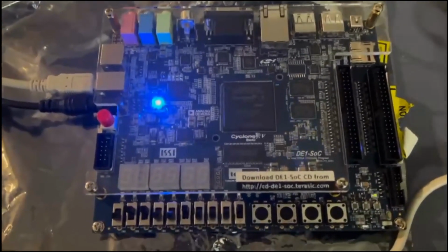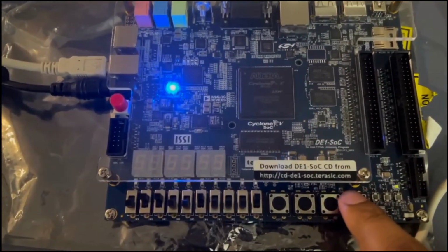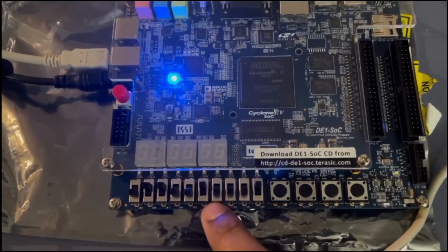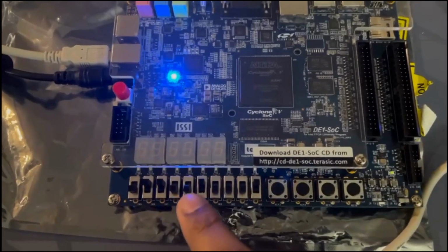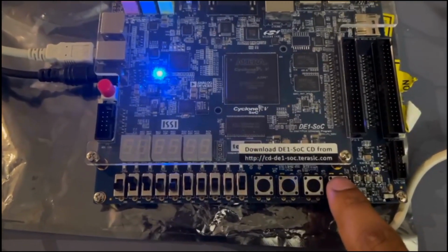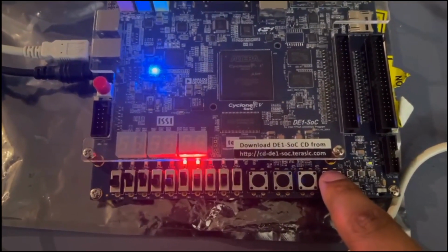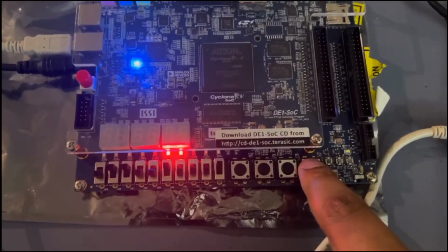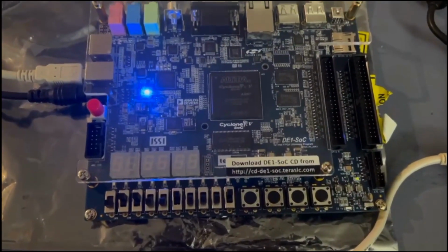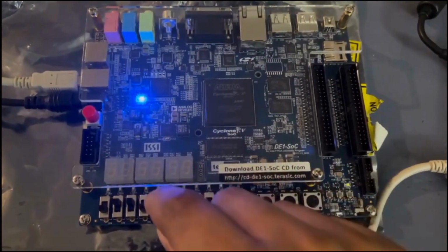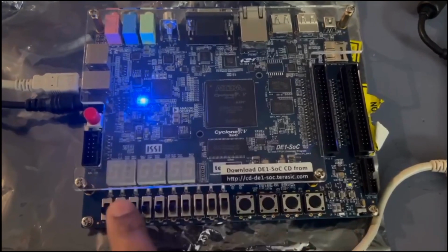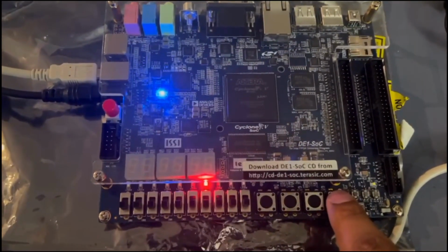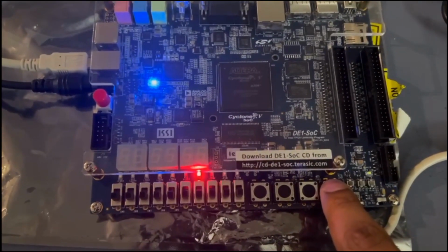As you can see, the current value is pi, and I have programmed it such that the upper 5 bits are for the cosine and the lower 5 bits are for the sine. Once I click this, as you can see, sine pi is 0 and cos pi is minus 1. Let's try with another example. Let's switch all things to 0. Now as you can see, when I hit this button, the cosine value is 1 and the sine value is 0.